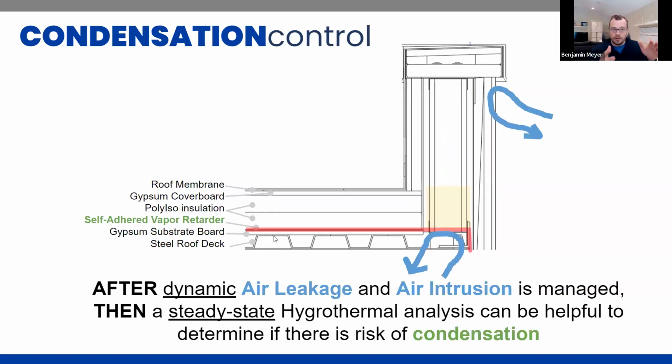And then the last one, working through this in a logical way. If you really want to stop condensation, you want to make your air barrier look as close to that ideal scenario we talked about initially as possible, where it comes across the roof and turns straight down. The challenge with that is you have to essentially plan for that. You have to build that along the way while you build your parapet, make it continuous, and fill that space. In that way, any air leakage is limited with your air barrier, and any interior moist air that wants to go past that and hit a cold surface really doesn't have a cold surface to hit. It's all been conditioned and maintained inside the building.